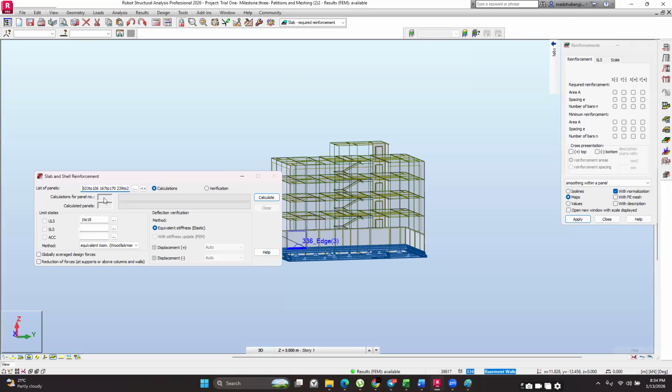This one is going to take time, and it is totally not required. I'd say it's not required because if these slabs are typical, then there's no point in designing all the floors. Just design for one floor and then use those results for the others. That applies only to floors that have the same layout.